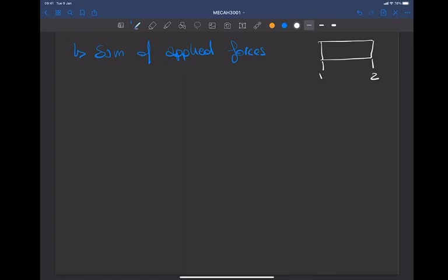So we basically have to consider the forces that can be exerted on the fluid and by the fluid in this configuration. As I said before, we can have three kinds of forces. We can have pressure, we can have forces on the wall, the shear stresses, and also the gravity and other volume forces.